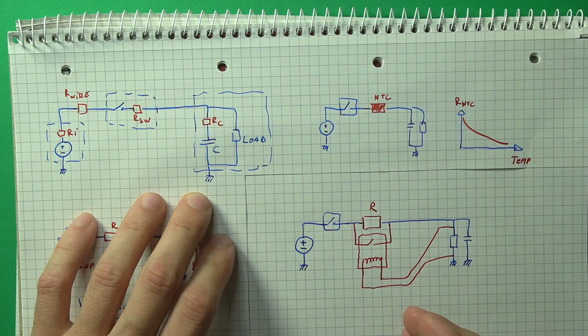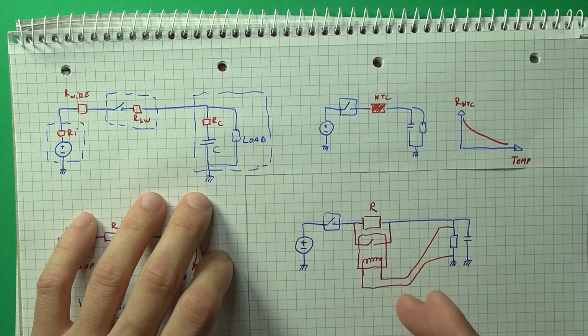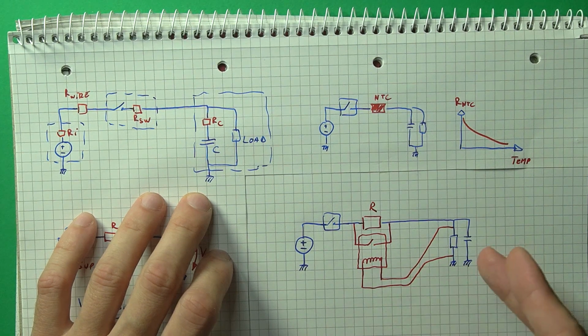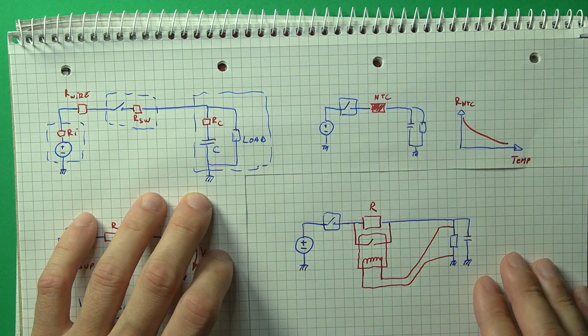This is worth doing when the energy required by the relay is far smaller than what would be wasted on the resistor. And depending on the use case, you may also want to add in time delay circuitry that activates the relay only after the load reached a certain value and a certain amount of time has passed.